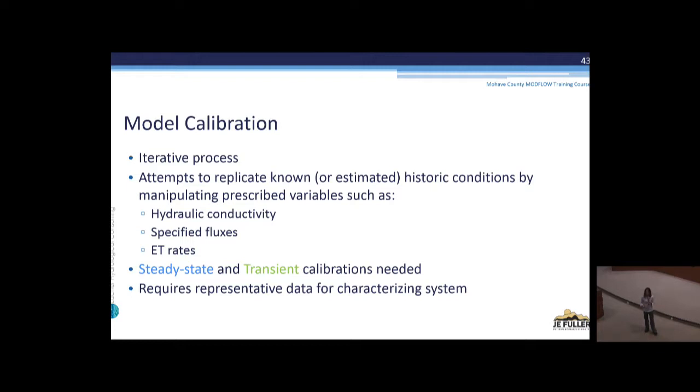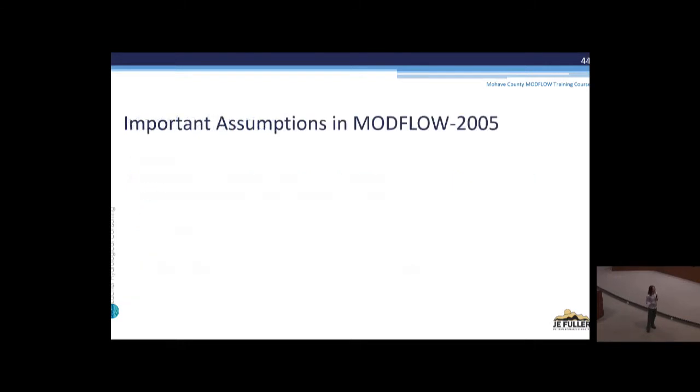You may think that you have a lot of resolution in your data, but if you look at the basin and see where your actual water level measurements are, and there's only 16 across the whole basin, a 1 kilometer grid might make sense. So it really just depends on the density of the data that you have and what you're trying to characterize.